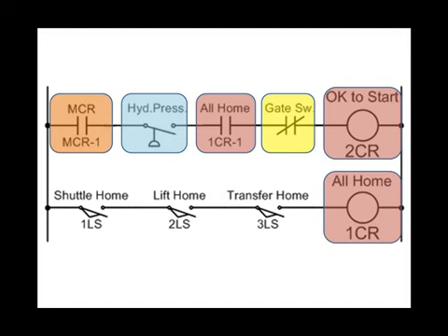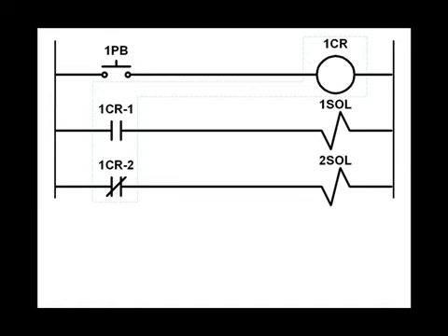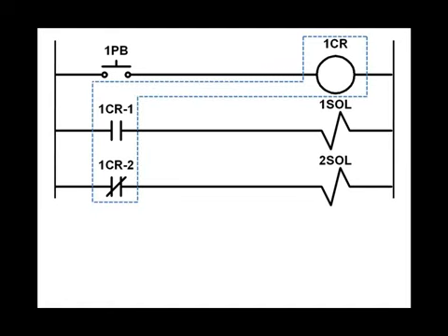Take a few moments and review this relay circuit. The object of the circuit is to control a cylinder with a double solenoid valve. The heart of this circuit is the control relay 1CR. In an actual relay control circuit, each set of contacts has a unique identification. Physically, the contacts and the coil are one device, but in the actual circuit, the coil and the contacts that are controlled by the coil can be separated onto completely separate sheets of the drawing set.